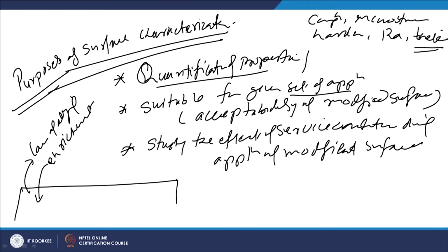Then there can be a change in microstructure due to prolonged exposure at a higher temperature. Change in structure can take place, which may appear in the form of coarsening or destabilization of certain phases. Prolonged exposure at a higher temperature may lead to the decomposition and destabilization of certain phases, leading to the formation of softer phases.